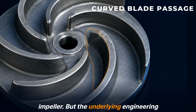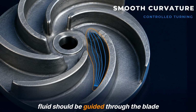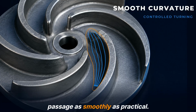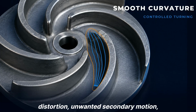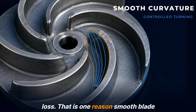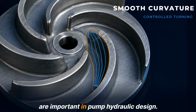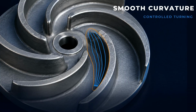But the underlying engineering lesson is still extremely useful. The fluid should be guided through the blade passage as smoothly as practical. Poor curvature or abrupt geometric changes can create stronger flow distortion, unwanted secondary motion, separation, and additional hydraulic loss. That is one reason smooth blade curvature and controlled passage geometry are important in pump hydraulic design.